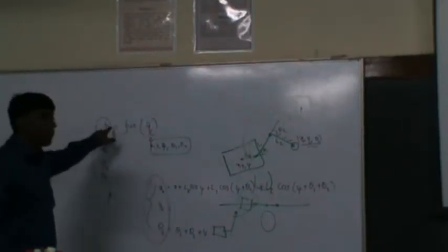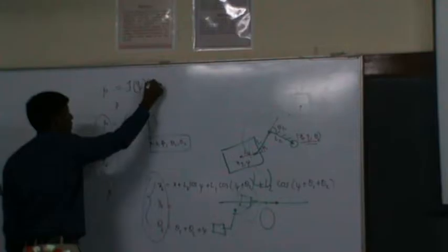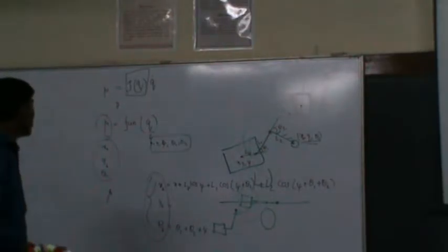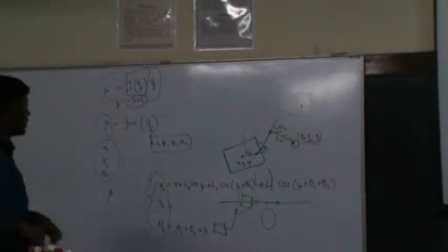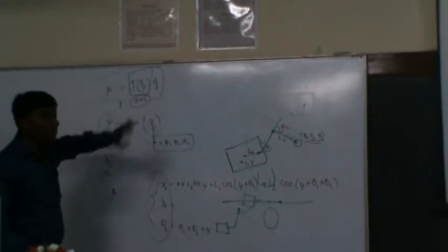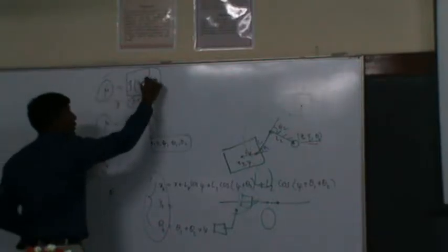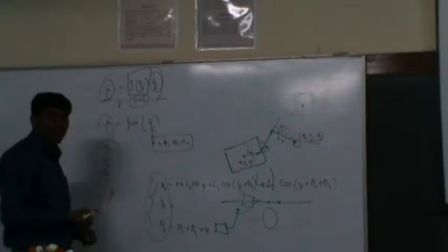Now if we differentiate this, we get the generalized kinematic equation, which gives mu dot equals J times q dot. This is what we call the Jacobian matrix, if you remember from your kinematics course. In this case, the Jacobian matrix will be 3 by 5. This is a rectangular matrix, correct? If you have a rectangular matrix, and it is an over-actuated or kinematically redundant system, you have a freedom, because this is known and you are trying to get this, or this is known and you are trying to get this. You have a link between these.